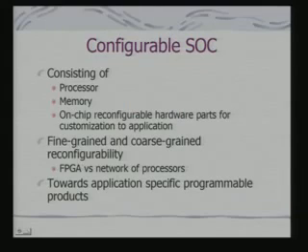And what we say is that it's a movement towards application specific programmable products. If I look at an ASIC, which is an application specific integrated circuit, there the whole design is targeted for an application, and the focus is not reprogrammability of that chip. Here we are talking about an application, no doubt, but at the same time keeping in mind the reprogrammability. Okay, so that means depending on maybe a change in the protocols, it should be possible for me to use the same hardware, reprogram it and make the appliance. I need not freshly design an ASIC.